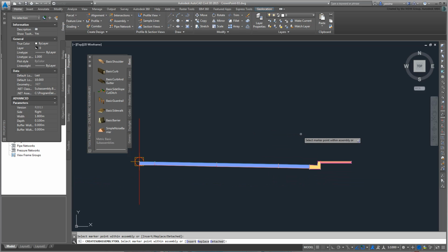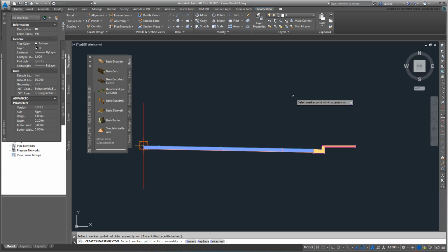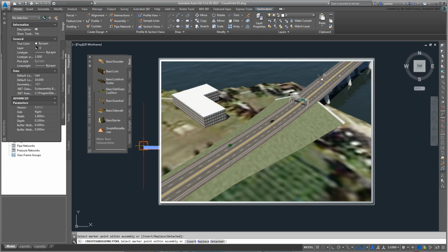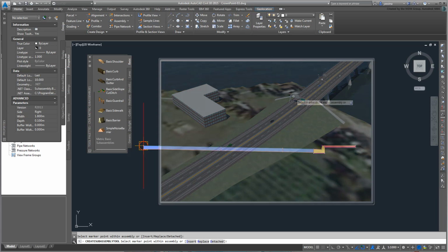You're almost done, but you still need a component named Daylight. A daylight in this context is a projected slope from the bridge design to the target surface underneath. It works in either cut and fill situations. In this case, since the design is higher than the surface, the daylight component creates fills to join the road edges to the ground.